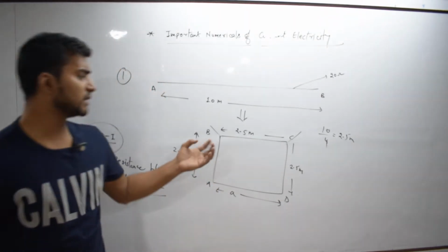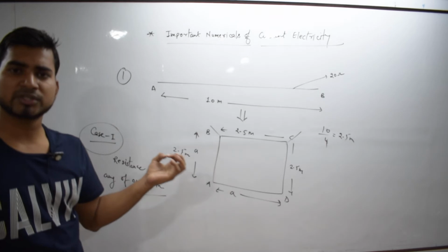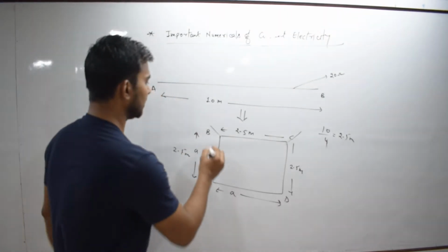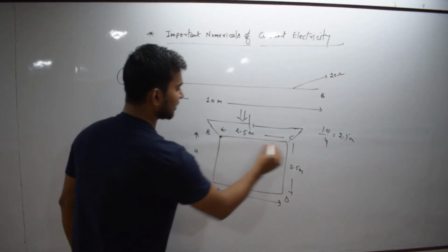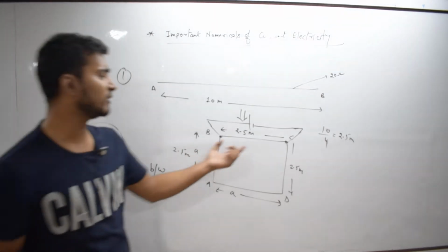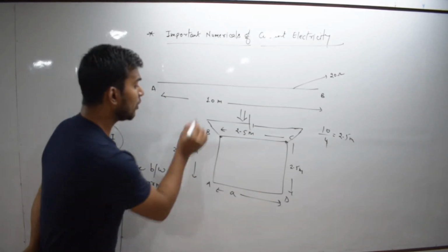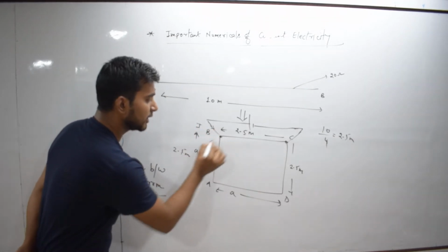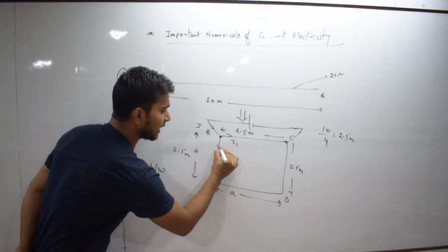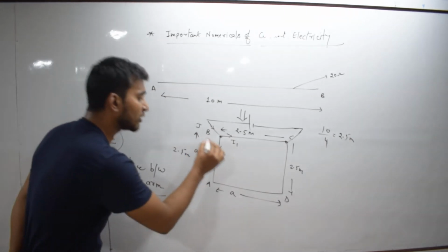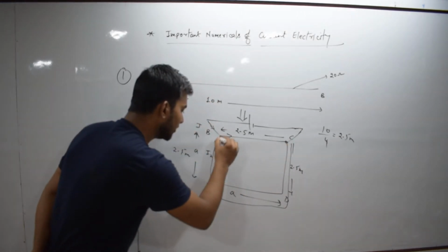Okay. Now the important thing is that we have to find the resistance between BC. Whenever this kind of question is given, you have to imagine that we have connected an external battery between BC. Whichever points are provided to you, you simply consider that a battery is applied between these two ends. Now let's suppose the total current is I. From this point the current will be divided. Let's suppose the current in this arm is I1 and in this arm is I2. Now whatever current is going downward has to follow the path from this end.